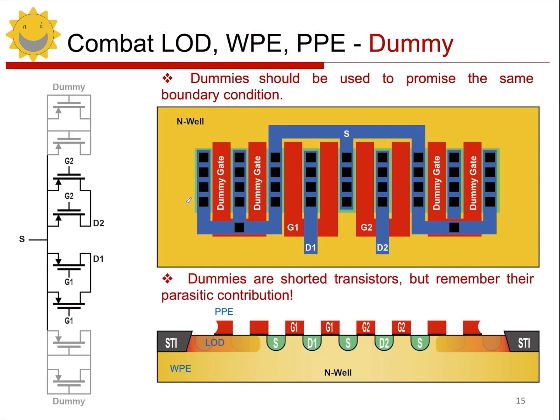Let's look at an example. So what example is it? This is its schematic, where we currently have two pairs of transistors, and the first and second, this part. So these are the first and second transistors. Of course, the first and second refer to the drain connections. Now, these two pairs of transistors need to be matched, right? So, for this part, we need to perform a matching operation between these two transistors and those two transistors.